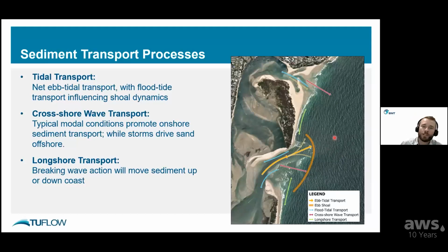Also important is the cross-shore wave transport. During modal wave conditions, or typical wave conditions, sediment tends to go onshore, but then during stormy conditions, that balance tips over and the sediment is driven offshore. And then of course we have longshore transport. Depending on which way the waves come into the coast, they will drive transport either up or down.